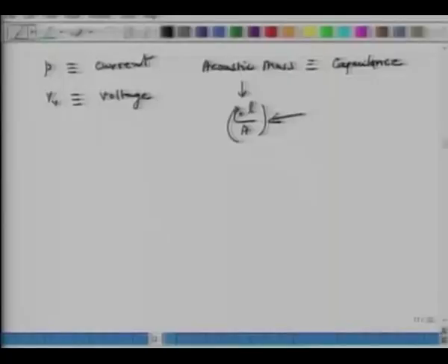So I can construct a circuit with short tubes, and these tubes physically can be fairly long. For instance, at 40 hertz, the length of a short tube will be anything less than lambda over 6, and the lambda for a 40 hertz sound wave will be 340 to 350 over 40, which is a significantly large number. So these are not like micro devices. These can be fairly long. So we talked about an open tube. Now we'll move to a closed tube.